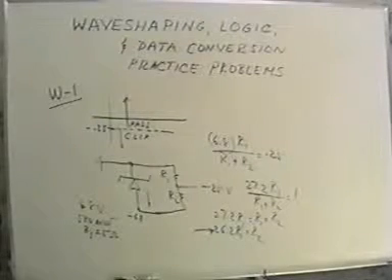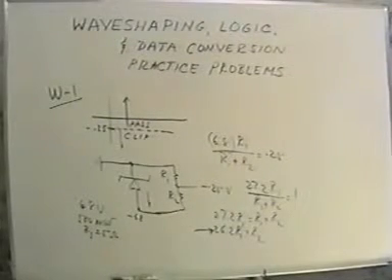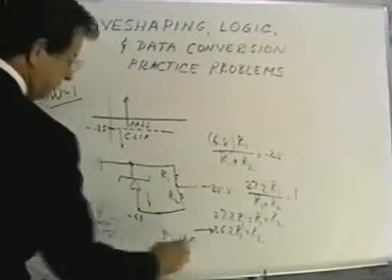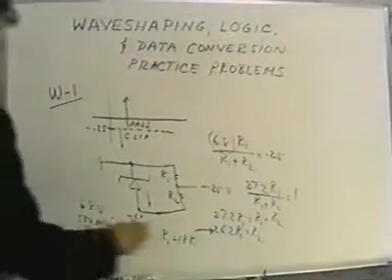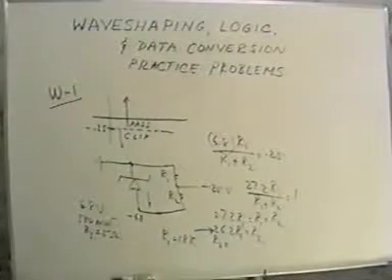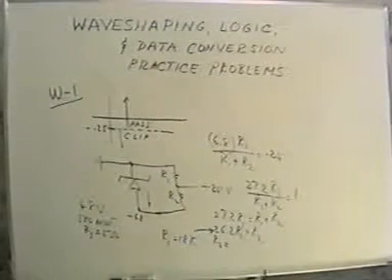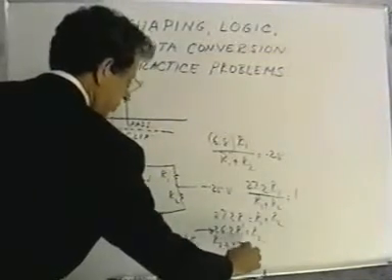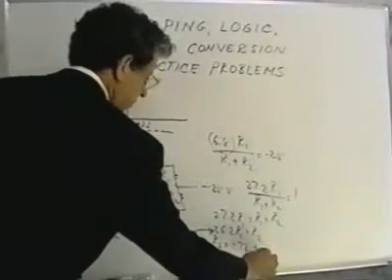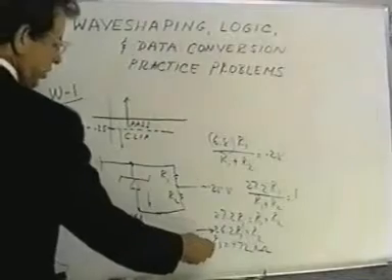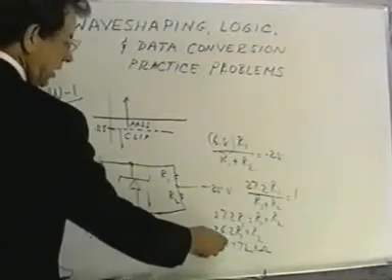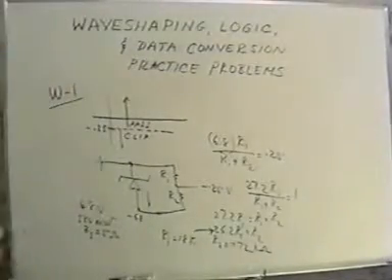So just pick some numbers. And a good choice, not the only choice, but let's pick R1 equal to 18K. If I did that, then R2 will be 26.2 times R1, so I need to multiply the 18K by 26.2 to get 472 kiloohms.